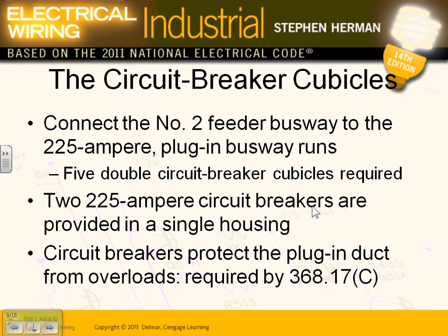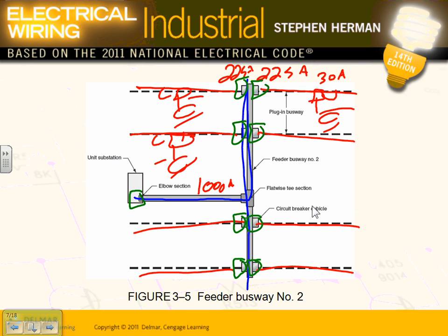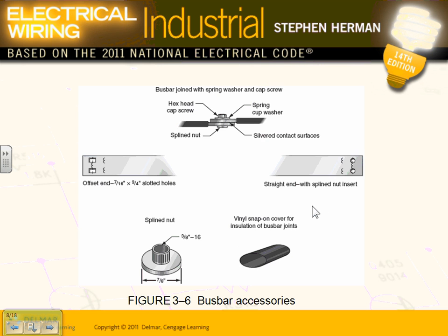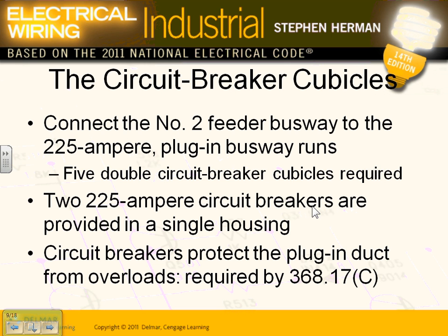This one right in here that I drew is called a circuit breaker cubicle. In feeder number 2, bus to 225 plug-in busways, remember that we have a 225 amp circuit breaker feeding this side and the other side. That's called circuit breaker cubicles, 225, two of them.